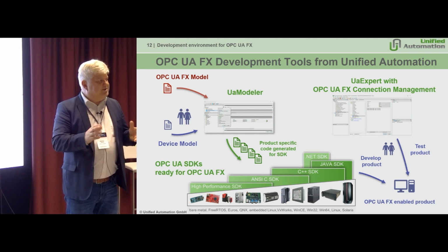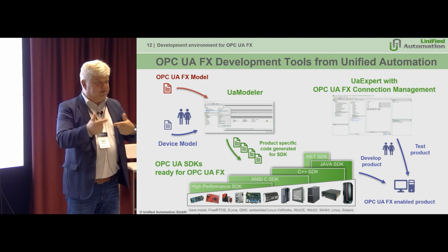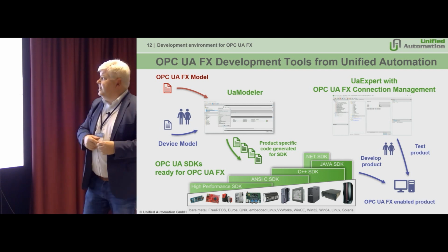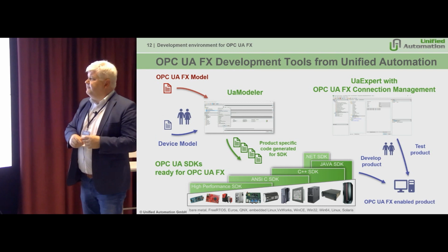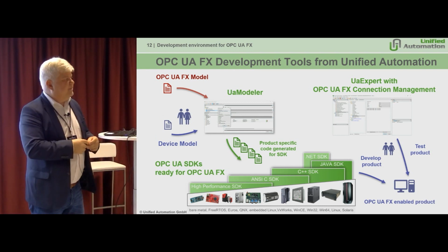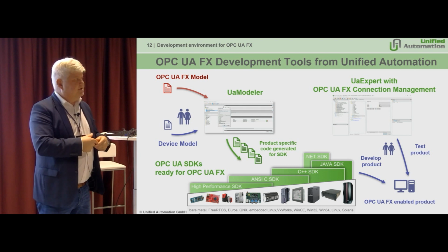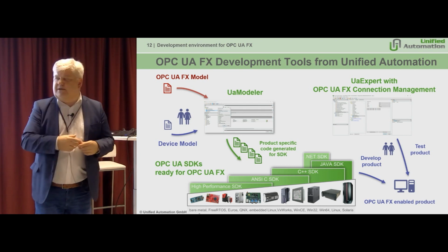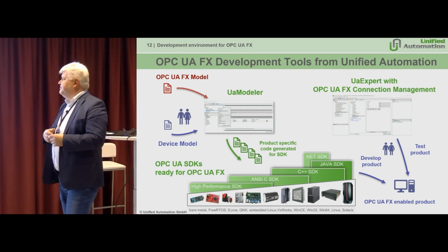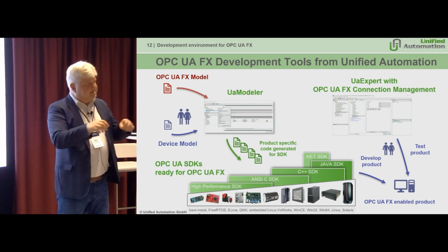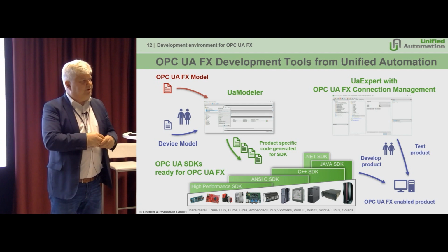Since version 1.7, it's also compliant with the latest OPC 10000-14 version of the PubSub configuration. And we added also OPC UA FX configuration in there. That is at the moment also available as a beta version, but will be available in the next 1.8 release. And then you can do the communication testing between automation components with UA Expert.